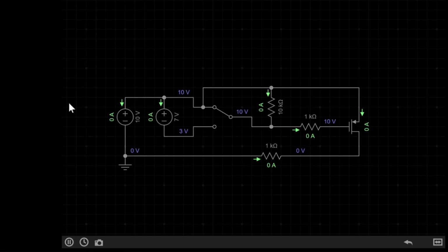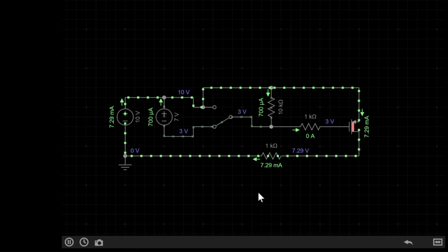Now looking back at our previous circuit, all the resistors perform the same role as they did in the previous circuit, except, as mentioned, our load is now after the MOSFET down here, and the gate resistor is now a pull up instead of a pull down, meaning it pulls the current up to the supply, so the gate current has somewhere to go. Before we finish the video, there is one more thing I need to mention.